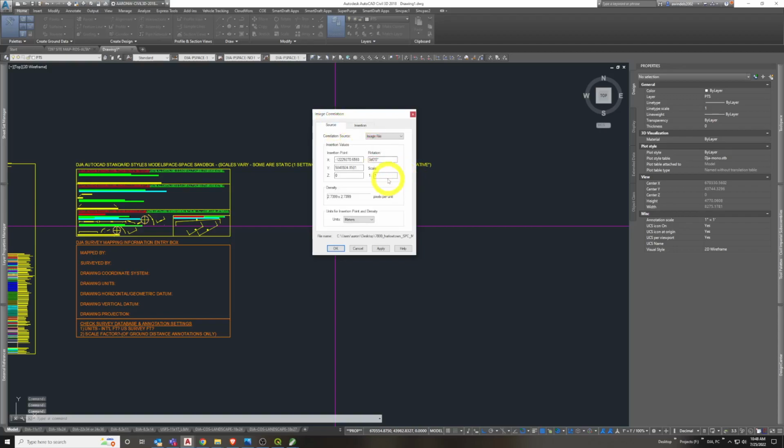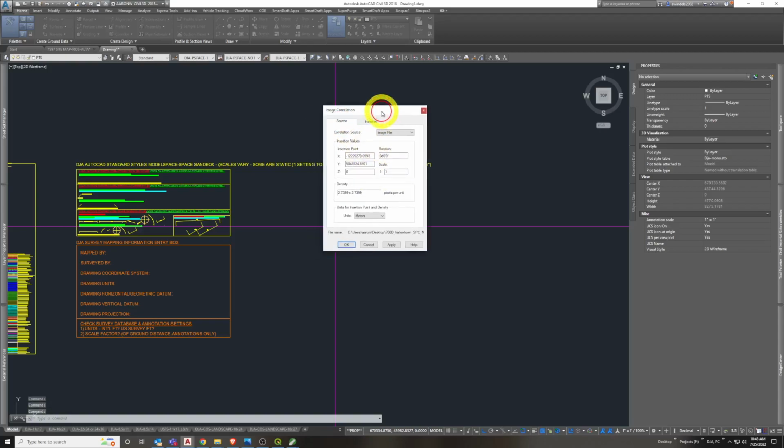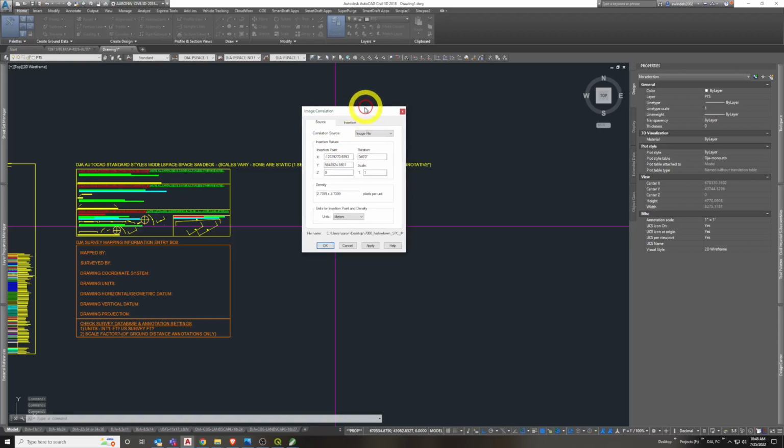So this is the error we've been seeing. This scale should be 1. In insertion, this scale should be 1. No idea what's causing this to go to 5,000, 8,000, whatever random numbers it populates. If you see this as a number, that's a problem. Try to get it inserted into a clean file or template. Let's bring it in. You can see there should be data here, an insertion point here. That's the metadata inside the TIFF file. Let's hit OK.